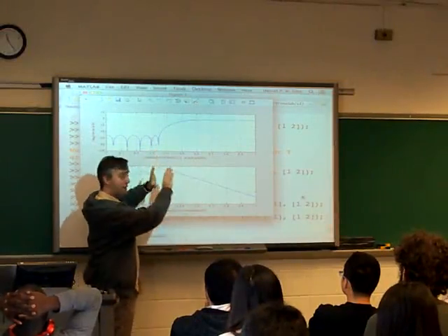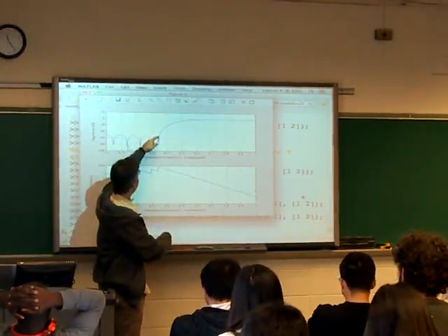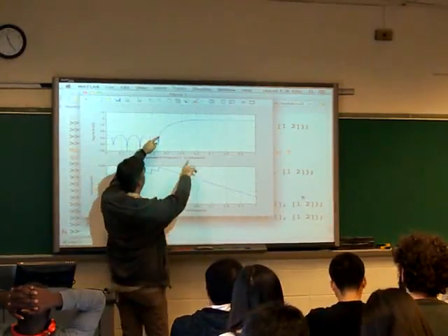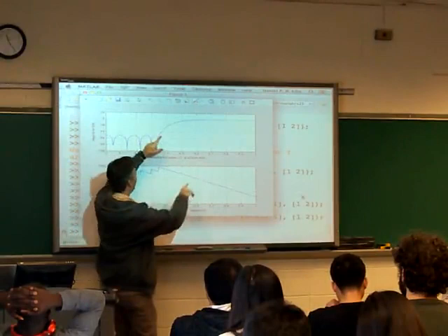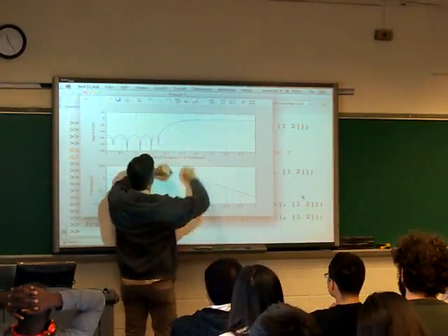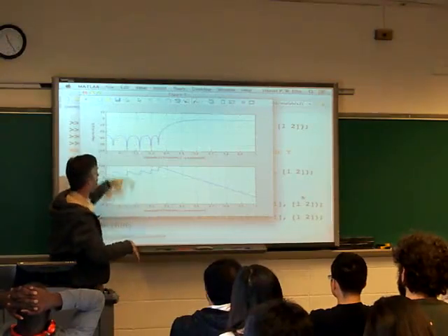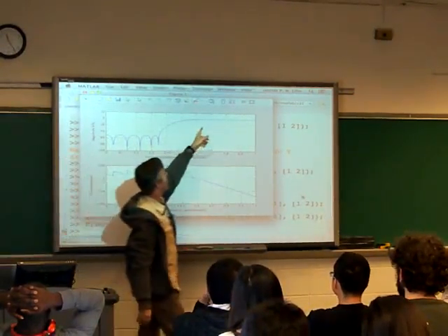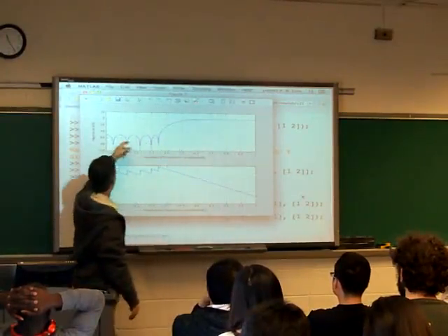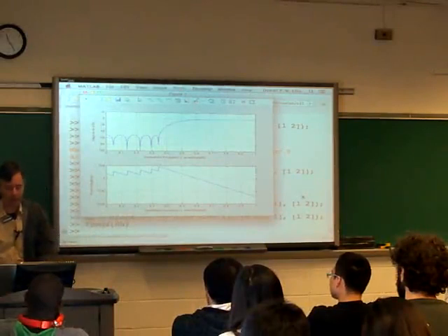we haven't reduced the width of the transition band, right? Because it's always just trying to match saying, well, we want the transition band from 0.35 to point whatever it was, 0.65 or 0.55, whatever. And so it keeps that the same, but it uses the extra order to push the errors down. In dB scale, right, it looks like there are no ripples here at all. That's just because these ripples, which are minus 50 dB, they're almost a thousandth.